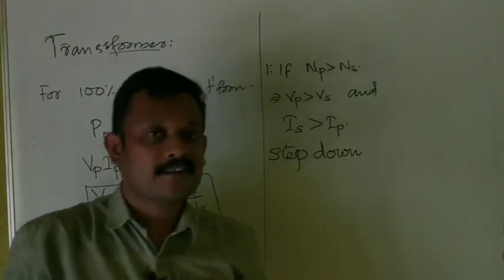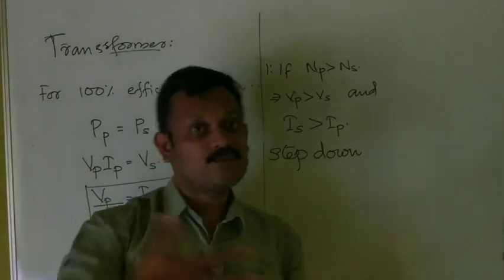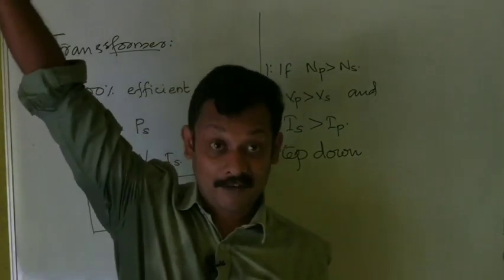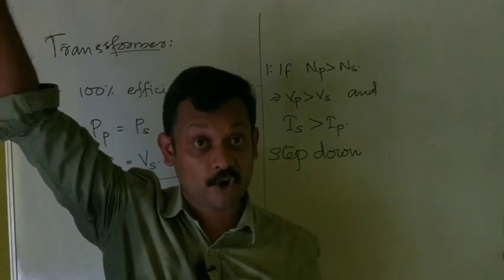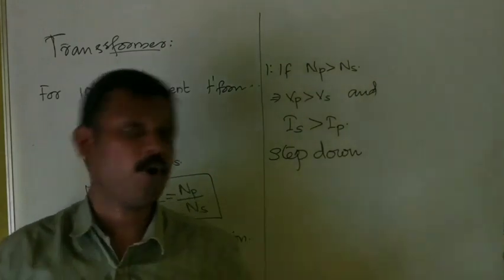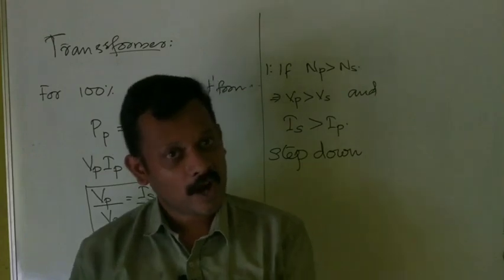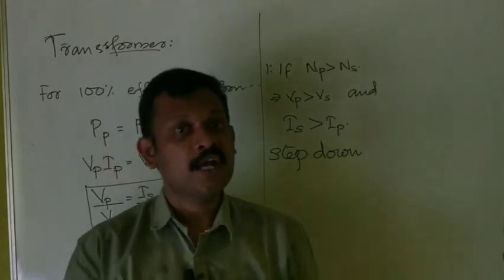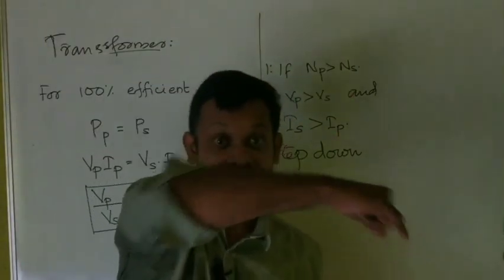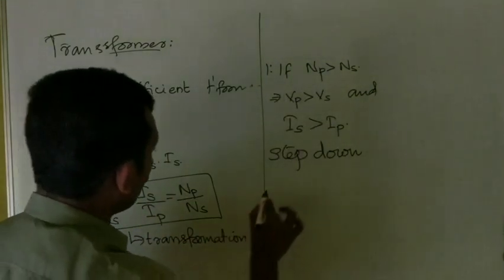We have learned in the chapter current electricity that power transmission occurs at high voltage, of the order of kilovolt. What is reaching our home is just 230 volt or 220 volt. That means the voltage of 11 kilovolt in the transmission line is converted to 230 volt in our home, right? That means the transformers that you see near your houses are step down transformers. There the voltage is reduced, subsequently the current is increased. That is what is done in the case of a step down transformer.